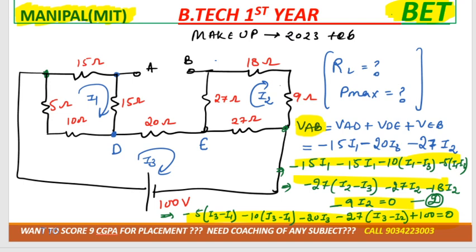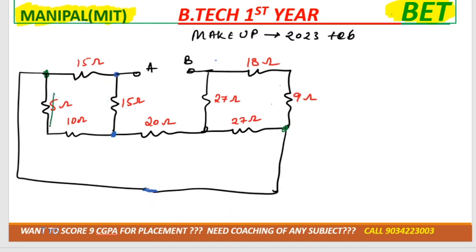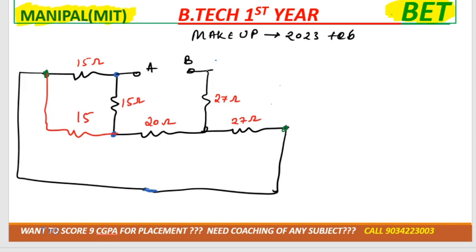Do it, draw the diagram. In this case 5 and 10 are in series, so I'm combining them into a single resistance, that would be 15 ohm. In this also 18 and 9 are in series, that would be 27 ohm, right?